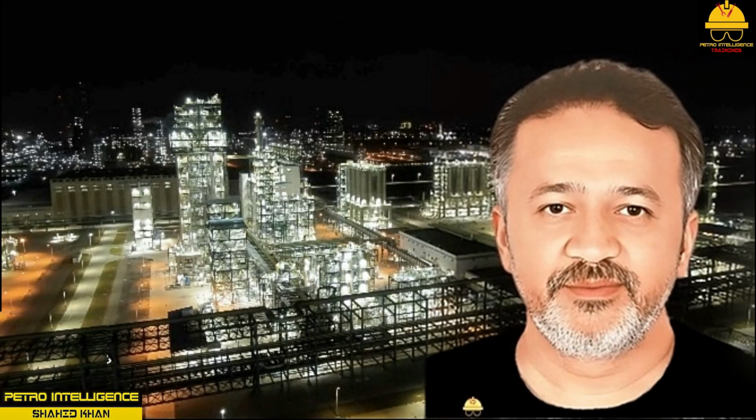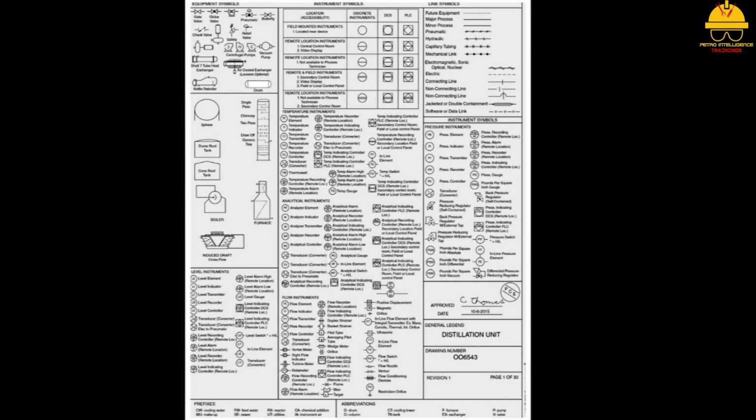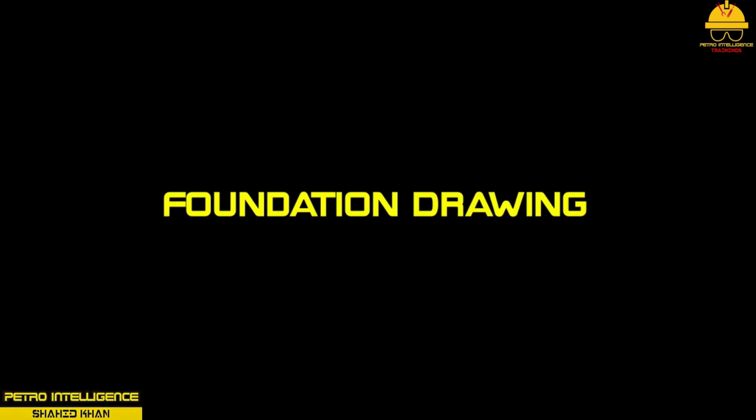Process legend. The process legend shown in this picture provides the information needed to interpret and read the P&ID. Process legends are found at the front of the P&ID. The legend includes information about piping, instrument and equipment symbols, abbreviations, unit name, drawing number, revision number, approvals, and company prefixes. Because symbol and diagram standardization is not complete, many companies use their own symbols in unit drawings. Unique and unusual equipment will also require a modified symbols file.